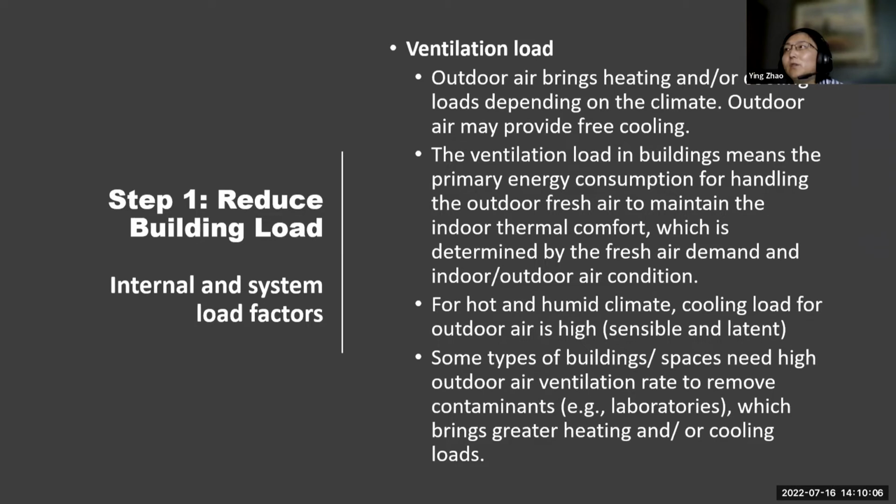And the ventilation load in buildings means the primary energy consumption handling outdoor fresh air to maintain the indoor thermal comfort. So that depends on the fresh air demand, that is the ventilation rate, and the indoor and outdoor air condition.